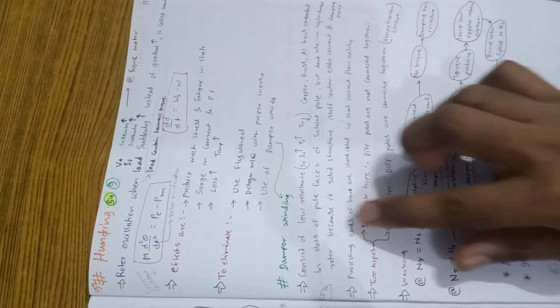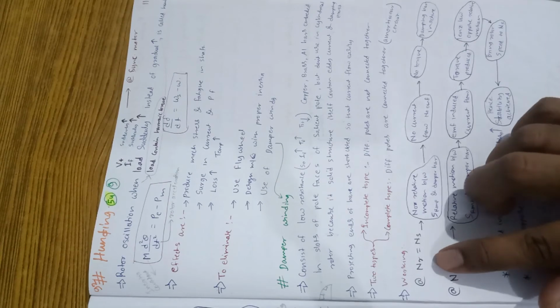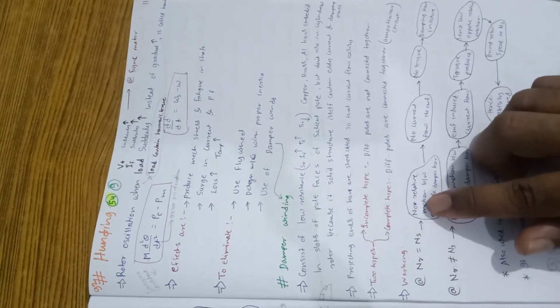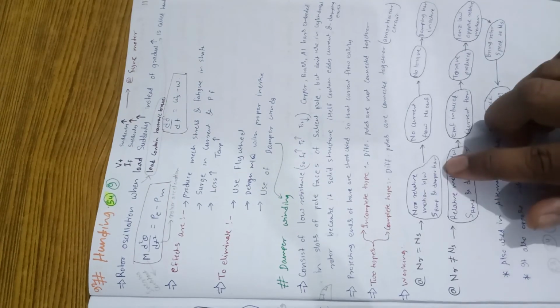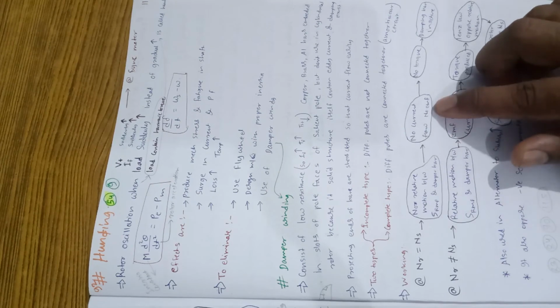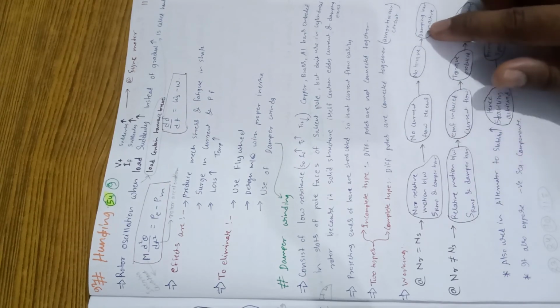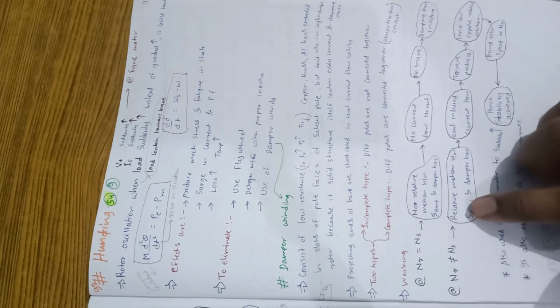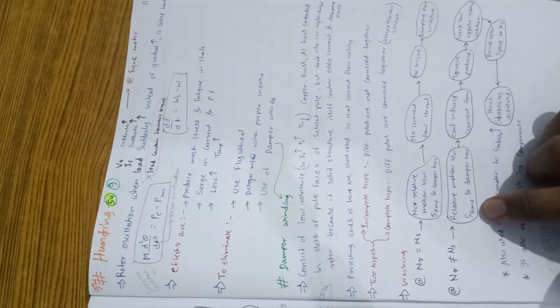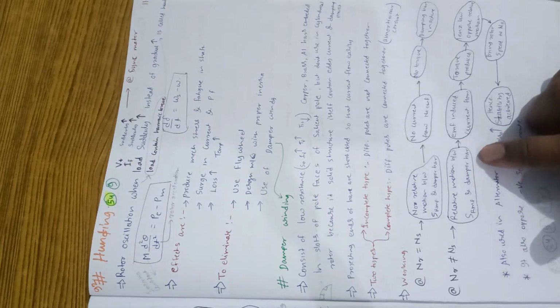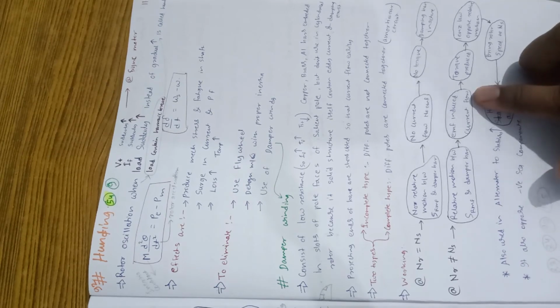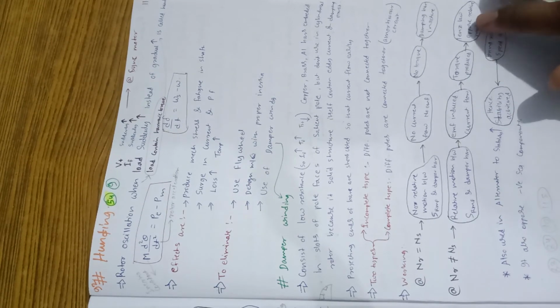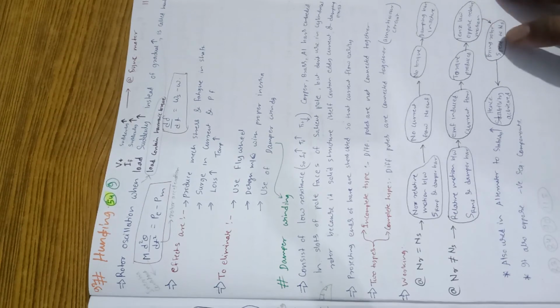How does this damper winding work? When rotor speed is equal to synchronous speed, there is no relative motion between the stator RMF and the damper bar, so no current flows, no EMF is developed, no torque is developed, so the damper bar is inactive in this case. When the speed of the rotor is not equal to synchronous speed, there is relative motion between the stator RMF and the damper bar, so EMF is induced and current flows. Torque is produced according to Lenz's law; it opposes the relative motion and tries to bring the rotor back to synchronous speed, hence stability is achieved.